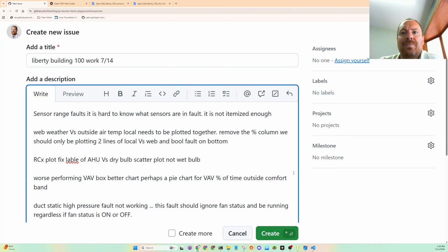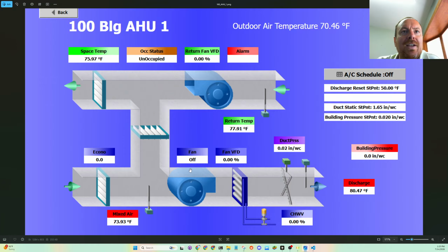What I mean by that is this is the fan command, and then usually there's a status right here linked to the little widget in the graphic, if you could see the animation. So this is probably working right for some reason, and the fan controls are going to 0, but this sensor is going through the roof.